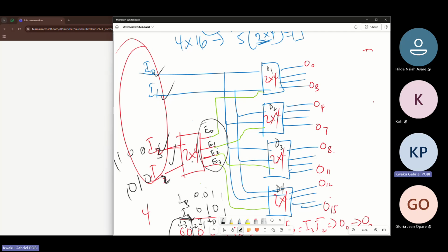This is also a decoder. The decoder outputs 1 at a time. So it means only 1 will be selected at a time. Then you think about it and go with an idea of using those outputs as the enable signals. So when each of them is activated, then it will activate the respective decoder it is connected to. That's all. That's all you need here. So this is how we implement it.